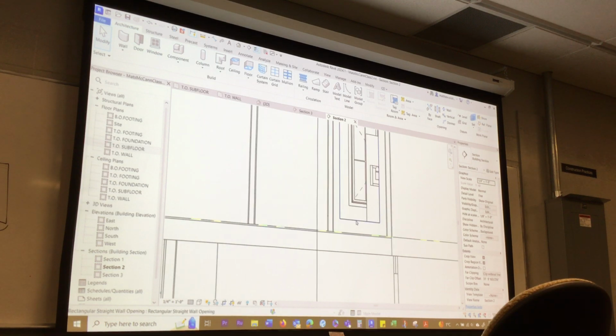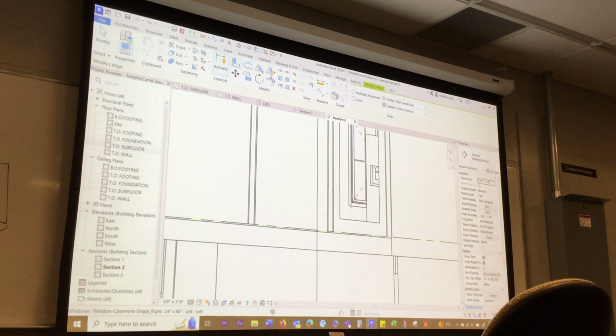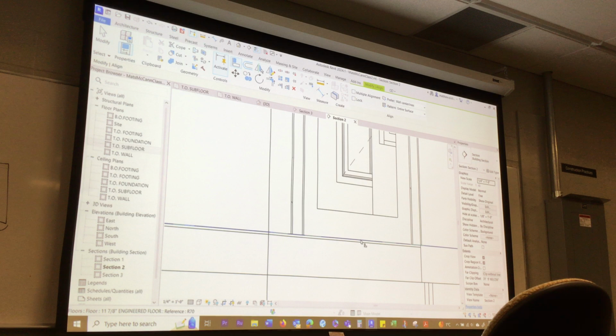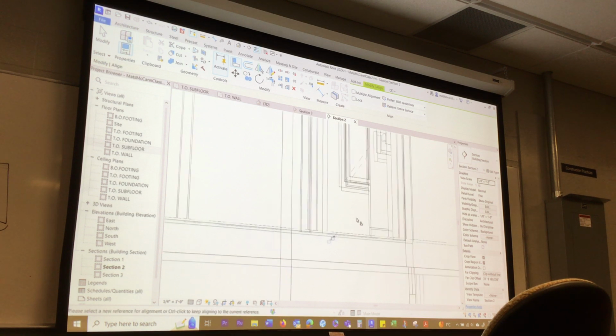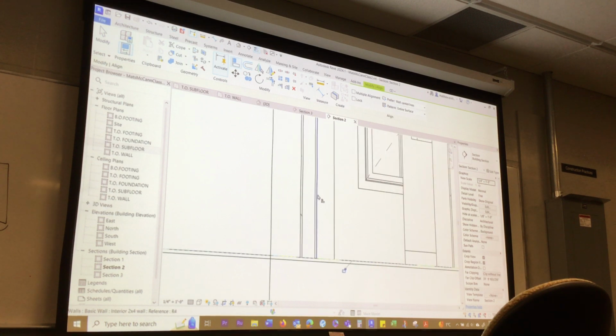Now what I'm gonna do is I'm gonna start lining. So I'm gonna grab the wall opening. I can pull it, but I'd rather not. I'm gonna use my align tool, and I want it to go to the top of subfloor. From there. I want it to go to the drywall, cause this is all finished in here, so I wanna go to the drywall, the hole.